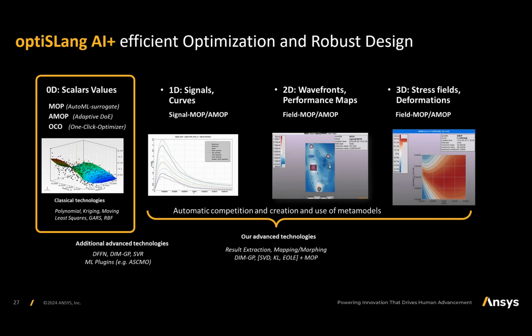There's also capability, similar to what you saw in SimAI, to take simulation results and create these surrogate models that are very fast. The constraint here is that you do need to parameterize your geometry, but if you're working with a consistent set of parameters, you've already defined this, then this could be a better tool. And today it's available on premises.